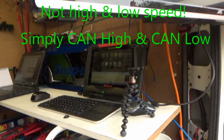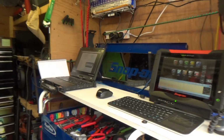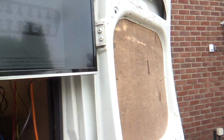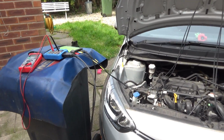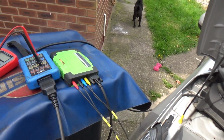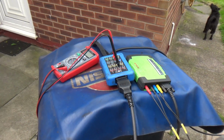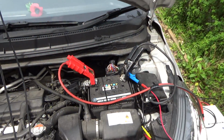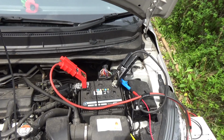And then we've got the laptop over there for the KTS. But yeah, that's all we really need, a basic scope. It doesn't have to be a Pico or anything like that. Basic scope, breakout box, DVOM, battery support, and somewhere to access the network. And that's about it.